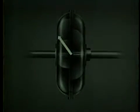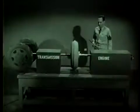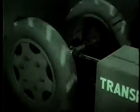This dual motion of the oil combining to send it in this direction. Increasing the velocity of these flows eventually transmits the torque, or turning power, from the engine through the fluid coupling's pump via the turbine to the drive wheels. When used in place of a conventional clutch, the fluid coupling is an effective liquid link between the engine and the drive wheel.